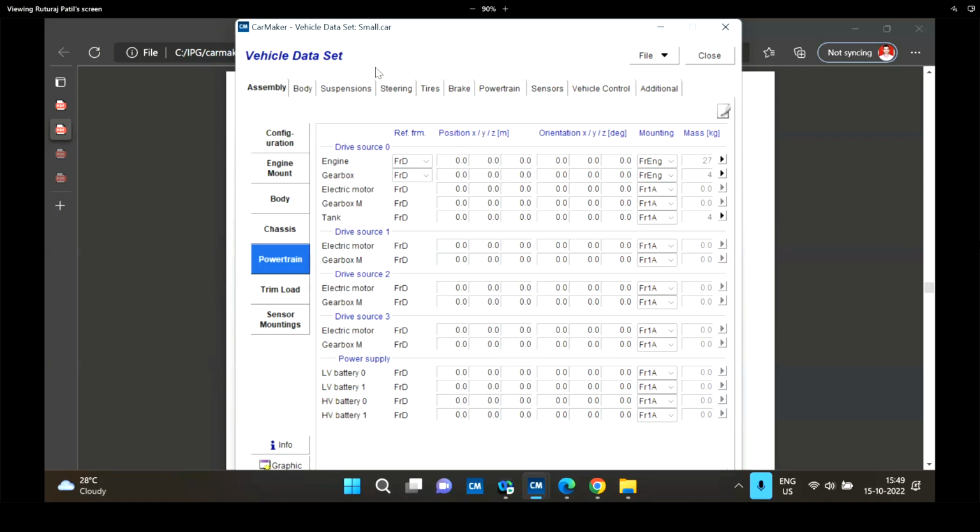In the later stages, once your vehicle has been manufactured and you have the actual dimensions, you need to focus more on the validation event. Right now, you can explore the software and the maneuvers part, the driver part, the scenario editor part, and parameters, and not focus so much on the vehicle data set.